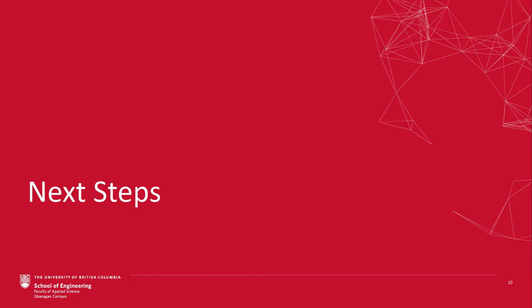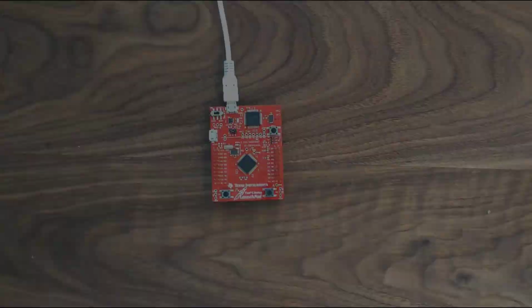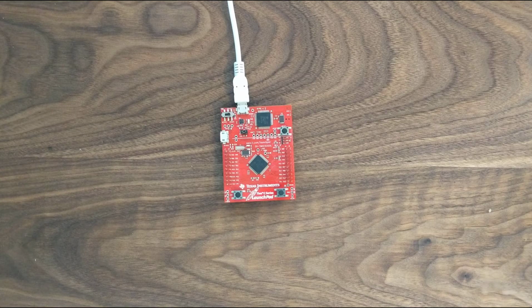Part 2, however, gets significantly more interesting. Instead of blinking 1 LED, we're going to be toggling 3. Done correctly, it may not appear as you would expect, seen here. The LEDs all turn on, but do not turn off immediately. Give thought to why this might be, and answer the question in the lab report. Lastly, in part 3, we will make a small change in the configuration of the semaphore with a significant change to the output of the LED, once again shown here.